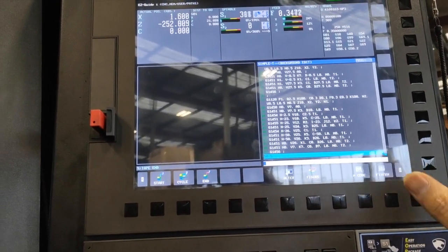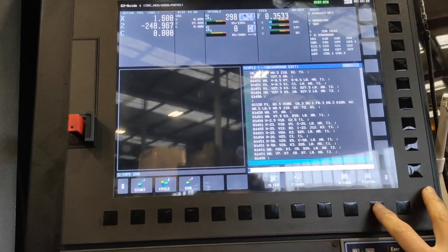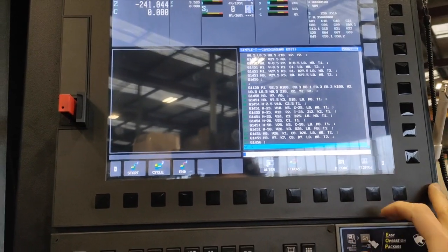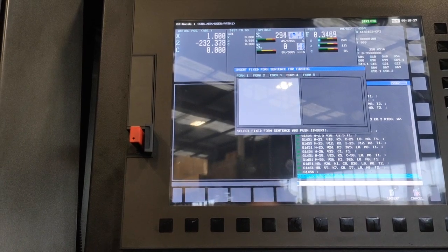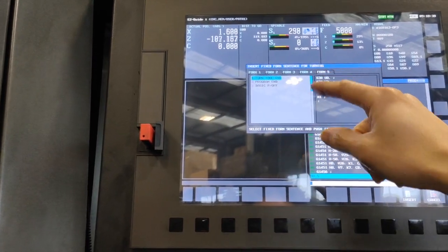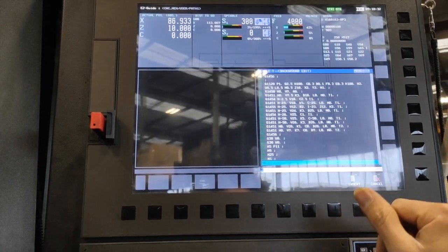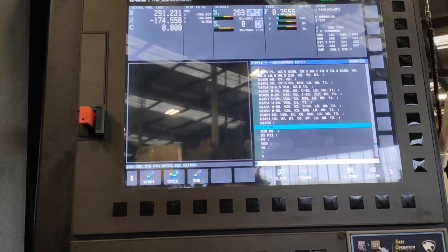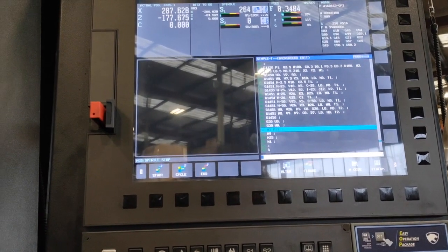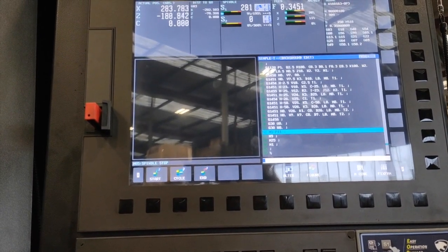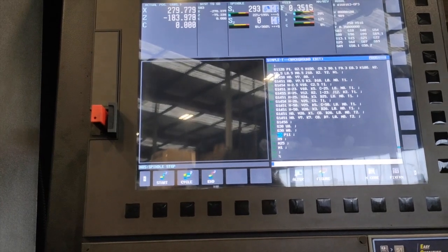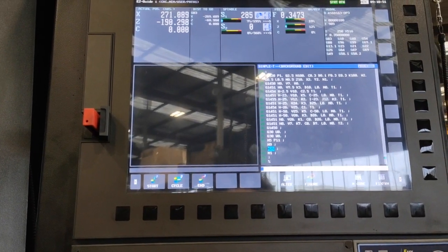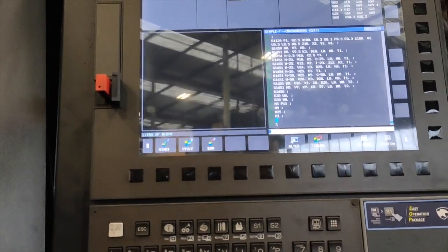Okay, and now, guys, you have your program, but we need to go to our tool end, go to fixform, and we are going to look for our tool end on our fixform. Insert tool end fixform. You have G30 U0 and G30 W0. Then stop the spindle, that is P11, on main spindle, and coolant. Then stop the conveyor. Then you have M01.